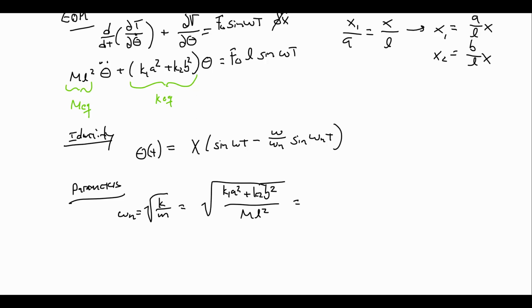And actually, when we do our calculations here, it turns out, because L is 1, that the numerical values of M EQ and K EQ are the same as they were the first time. But I want to point out that actually the natural frequency is the same no matter what degree of freedom we are working with. So it does turn out L is equal to 1, so it simplifies down. But even if L is not 1, our natural frequency is not affected by a change of coordinates. If we did this in x, x1, x2, theta, the natural frequency would always be the same, of 5.59. So that did not change.